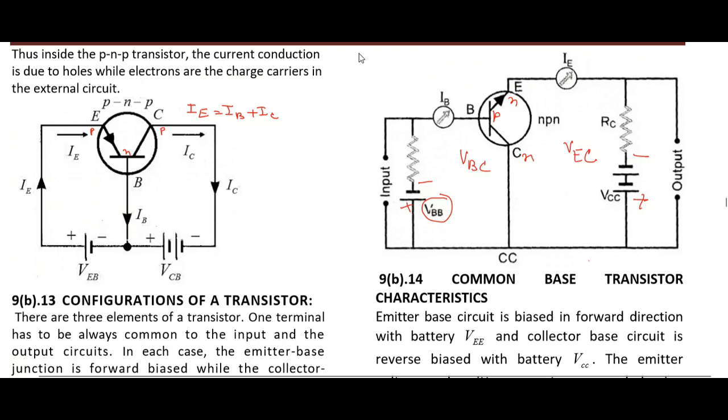And in this circuit there is a pitfall, because this is the collector base junction, it is to be reverse biased. This is P, connected with negative, and collector is connected with positive. This is the emitter base junction and this is emitter. Emitter has to be forward biased. For this forward biasing, N should be connected with negative, and this is correct.